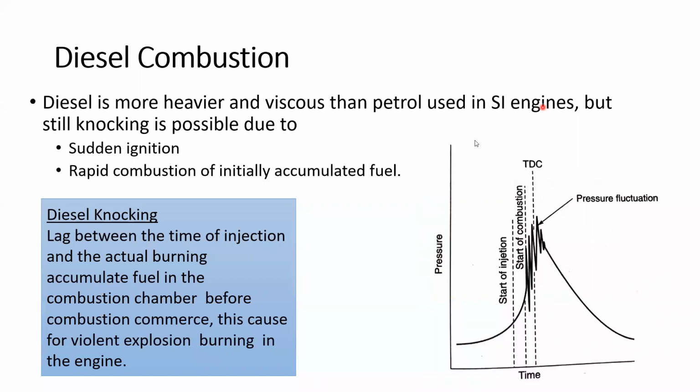In such a case you can actually hear a sort of violent explosion sound inside the engine. It's out of the ordinary. The engine normally makes a certain sound, but something is off from that. If a somewhat off sound is coming from the engine, and there's no rhythm in it, it's missing here and there.